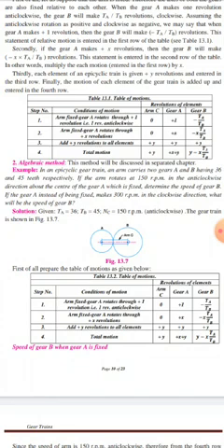So in the diagram it shows gear A and gear B meshing with each other, and there is an arm C. Gear A has 36 teeth and gear B has 45 teeth. The arm is rotating at 150 rpm in the anti-clockwise direction. So we have to find the speed of gear B if gear A, instead of being fixed, makes 300 rpm in the clockwise direction.